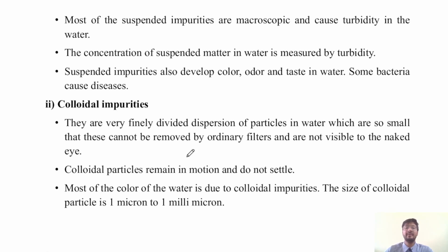Most of the suspended impurities are macroscopic and cause turbidity in the water. The concentration of suspended matter in water is measured by turbidity. Suspended impurities also develop color, odor, and taste in water. Some bacteria cause disease. Turbidity is measured by a turbidity unit like NTU, meaning nephelometric turbidity unit. Turbidity can be removed easily through settling or filtration.